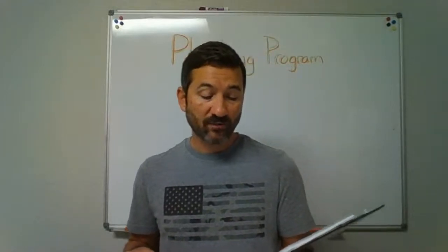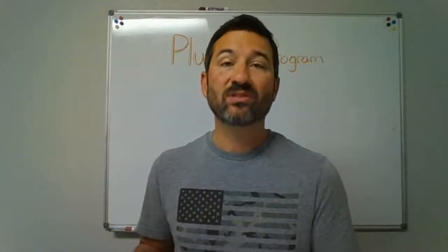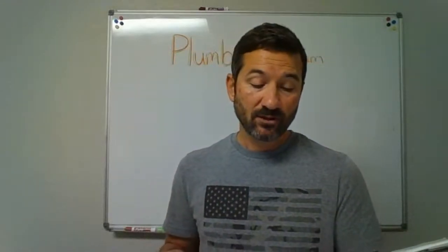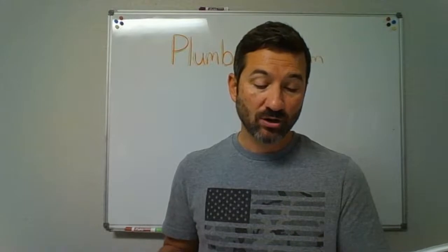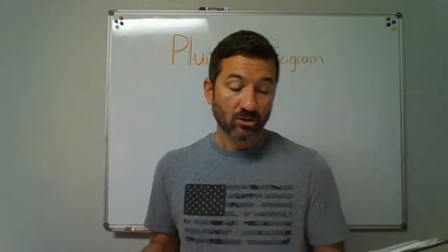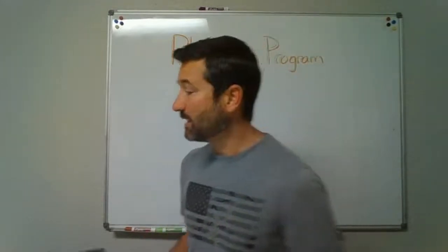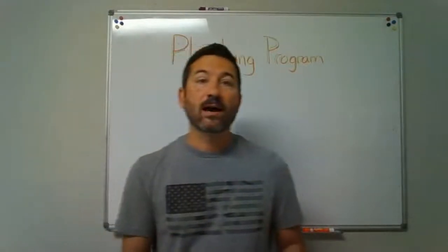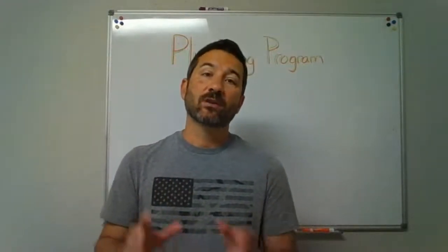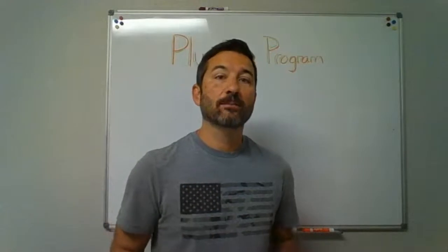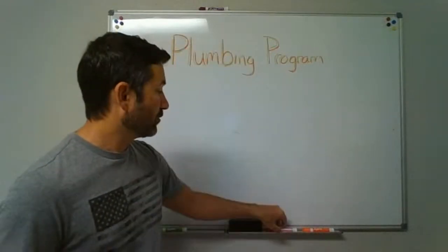Each trap and trap fixture is permitted to be provided with an individual vent. The individual vent shall connect to the fixture drain of the trap or trap fixture being vented. So that is one of the methods, an individual vent. So if you've got one trap fixture and you've got one vent that serves that trap, it says that's an individual vent.